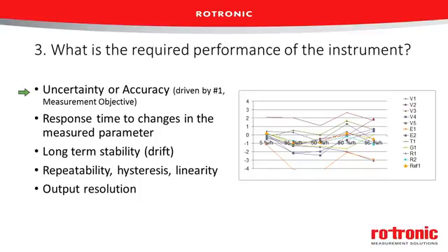One application where that comes to mind for this is looking at stability chambers. Here our requirements, the ICH would have defined for us that we need to have our stability chamber within plus or minus 2% RH and plus or minus 0.5 degrees C. So that helps us make a determination of what our requirement is.